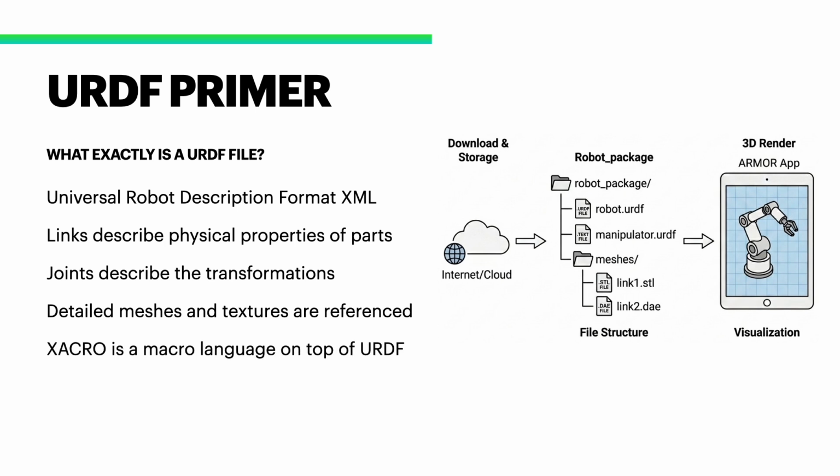Lastly, a related format to URDF is Xacro, which is a macro language. This allows embedding variables or commands or including reference to other URDF files, allowing organization and streamlining of large projects. The latest release of ARMOR supports Xacro projects in its loader code.